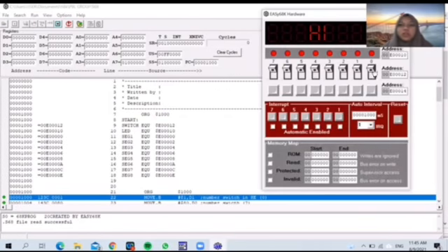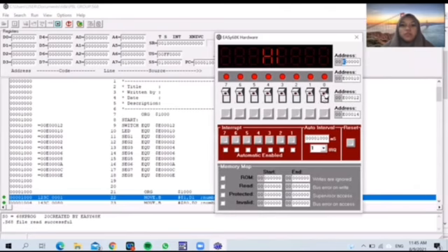So here, where we didn't run anything, and once we set switch number 0, it will display hot, and LED from 3 to 0 will blink. Then switch off and switch on number 7, LED 7 will blink, and it will display cool. And when I turn on both switches, it will state cool, hot, and all the LEDs will blink.